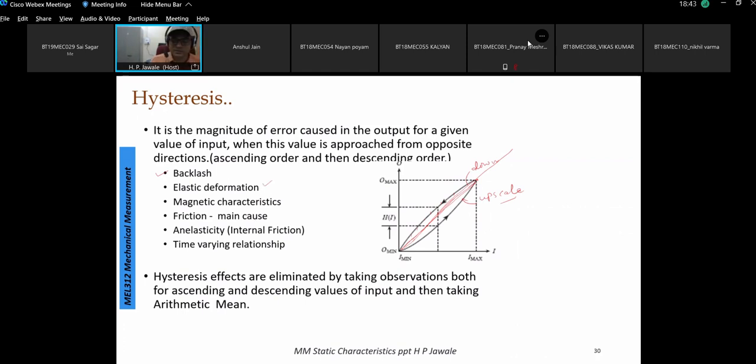Say for example, the elements will undergo deformation, and unless it is taken completely because of the flexibility, it is not going to show any motion transmission from one point to the other. Take an example: this is a flexible component, and this is lever 1, this is lever 2. I want to transmit motion. You can see this one now is touched, and it takes some motion, and then after it starts moving. So it's because of elastic deformation.